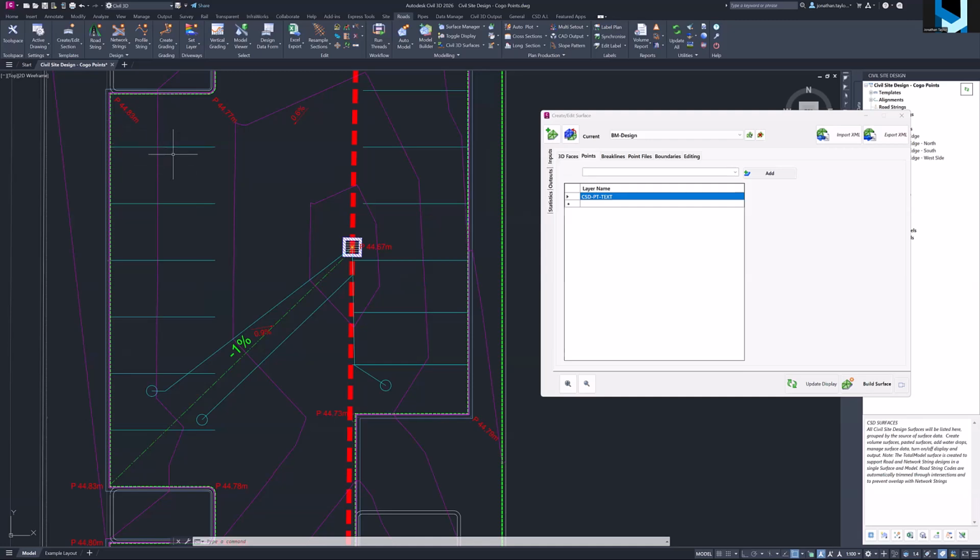This is actually quite a complicated job, because if you've got a slab through here, you could assign to the back of the curb a code that's a millimeter away with 150 mil of concrete, and then put 150 mil of concrete with 0 width on the edge of this slab. I did try this, and you actually get this slab surface being projected around the back.